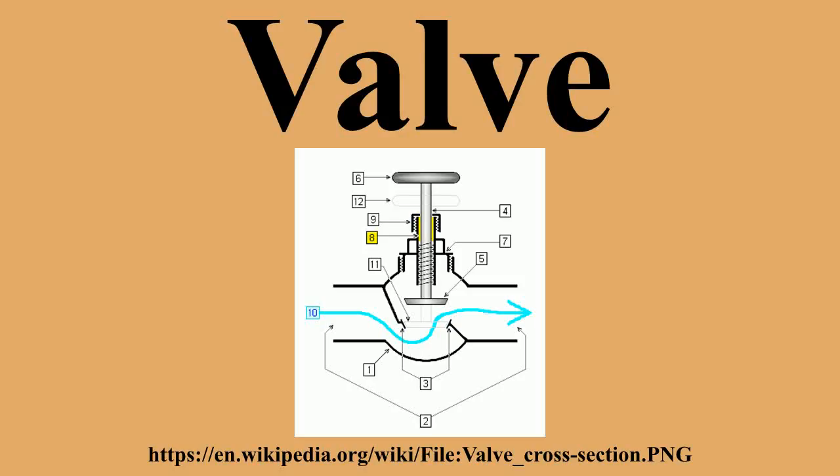Examples of normally open valves are purge gas supply valves or emergency relief valves. When there is a problem, these valves open, causing the unit to be flushed and emptied. Although many two-way valves are made in which the flow can go in either direction between the two ports, when a valve is placed into a certain application, flow is often expected to go from one certain port on the upstream side of the valve to the other port on the downstream side.